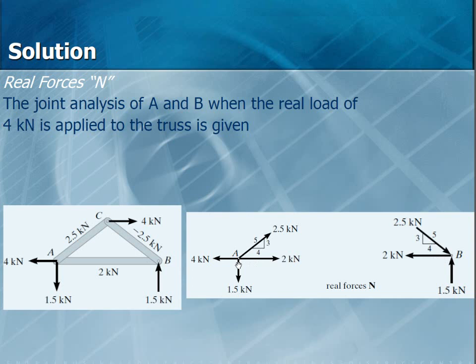Imagine if you have a long truss, it's going to take time to calculate, but this is the only way we have to easily calculate the deformation or displacement, the deflection in a truss. So you analyze it, then you get the capital N's. We call them the real forces, the real internal forces, because they come due to the real force.